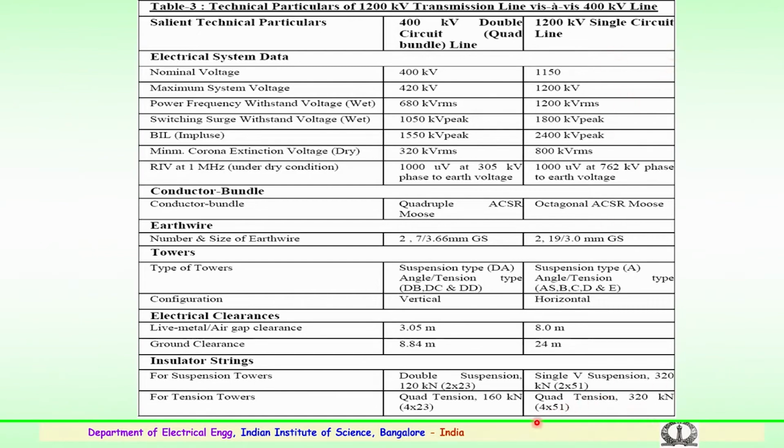You can imagine, 200 insulators, each insulator typically weighs around 12 to 15 kgs. So, you can estimate the total weight of an insulator string including the line hardware, the yoke plate, and the corona control rings near the tower. Every important aspect, these are the things to be considered for the mechanical loading of the tower, the estimation of the tower height, the clearances, and so on and so forth.